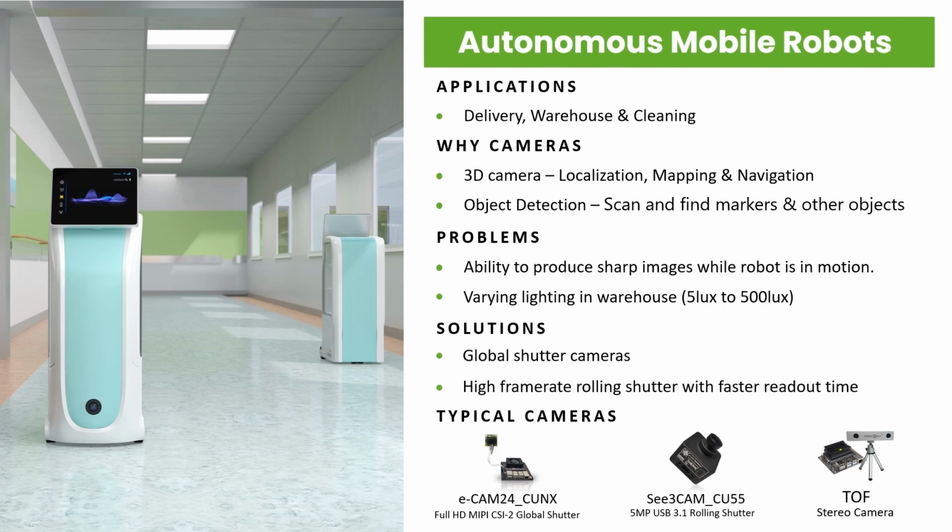For example, 3D cameras are used in an AMR for understanding its immediate surroundings and for obstacle avoidance. The 3D cameras can be based on stereo vision or time of flight technology. They both are capable of capturing the surroundings in 3 dimensions. This helps an AMR to recognize obstacles in its path and move around them autonomously.